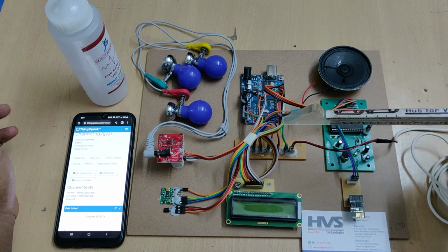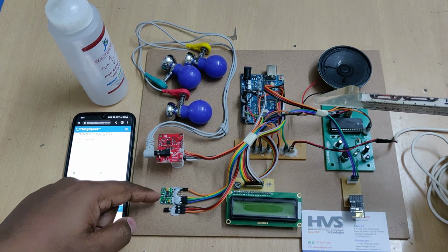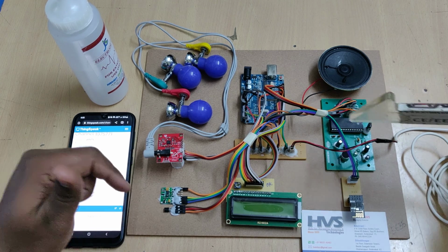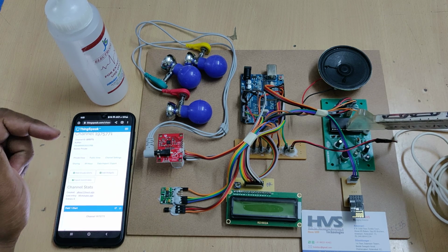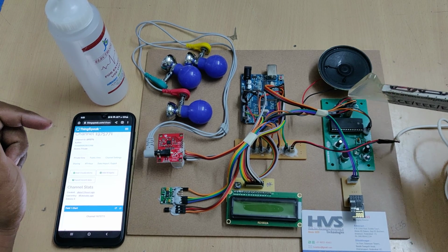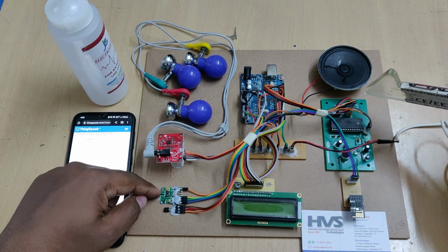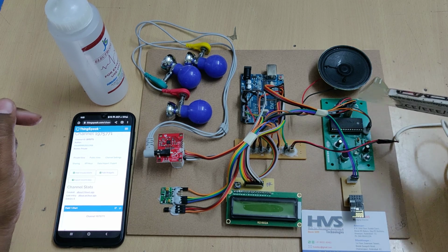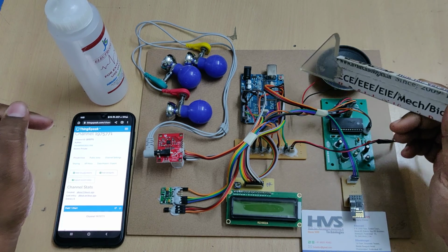And also if any abnormality is detected, if the temperature is above 100 degrees Fahrenheit, or if the heart rate is below 50 beats per minute or above 100 beats per minute, then there will be a voice announcement from this APR33A3, which is an audio playback recorder. We have already stored voices inside it in the respective pins: high temperature, low heart rate, high heart rate and low SpO2. These four pins are connected at pins 8, 9, 12 and 13 of our UNO board.